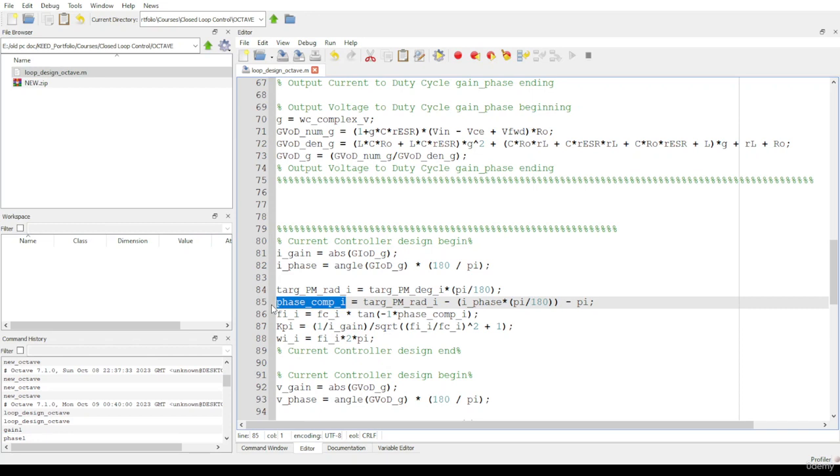But in power supply closed loop controller design, digital control loop design for power supplies essentially, lead compensators are often impractical. They're not very practical to be utilized in this scenario. So what you actually want to do is use a lead lag compensator. In digital control systems, lag compensators are very much favorable.